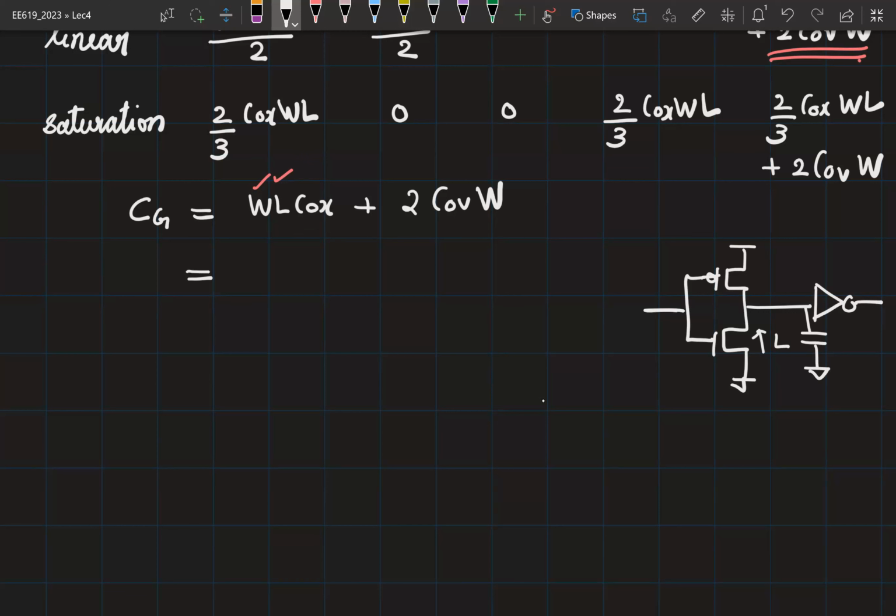The other part to think about is, if I make the length of all transistors larger, the gate capacitance of this inverter is also going to increase, because CG is proportional to length. So increasing length actually has two problems. One, it is going to increase the capacitance. Two, it is going to reduce the amount of current available for you to charge or discharge the capacitor. So I is decreasing, C is increasing. Effectively, your delays are simply going to increase.